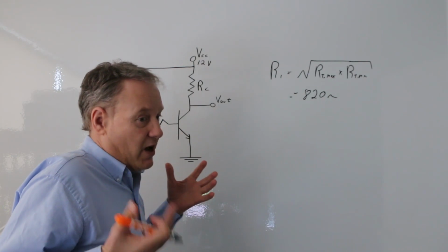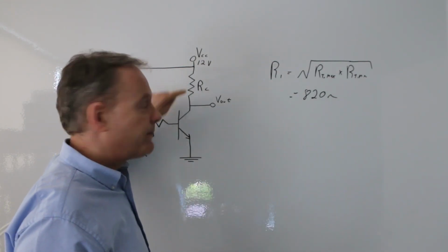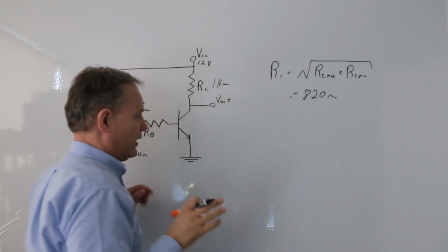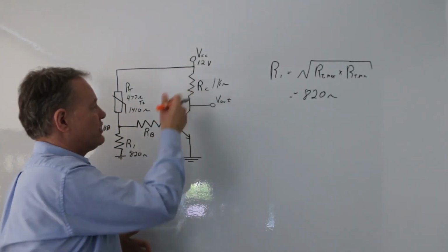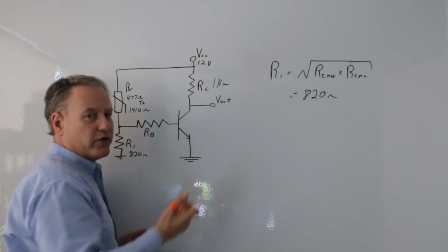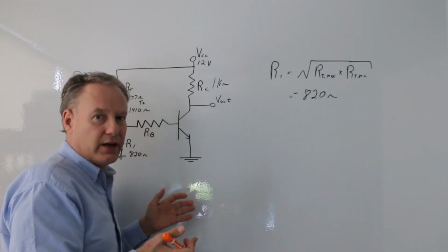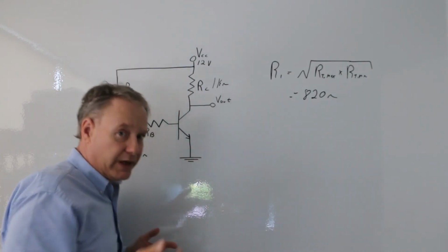So if I used a minimum 10K for my tie-down resistor, I use a 1K here. So I'm going to make this 1 kilo ohm. And we're good with that. That's not going to draw very much current. No matter what this is, whatever the current going through here, if there's enough current going through here that this is saturated, then the maximum current that this thing can draw will be drawn.